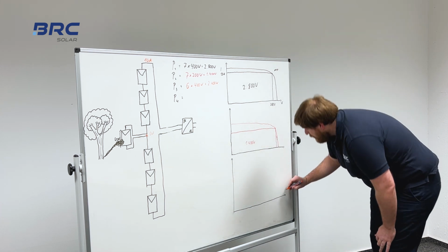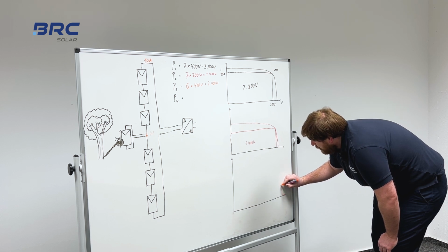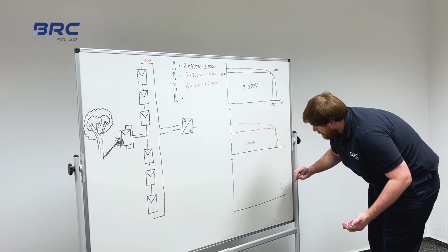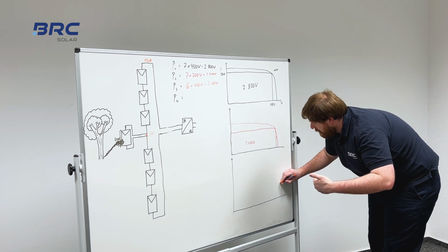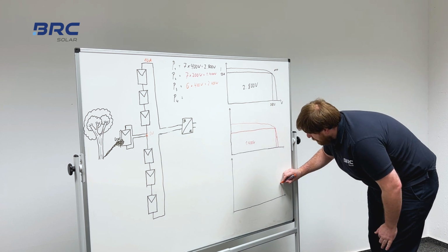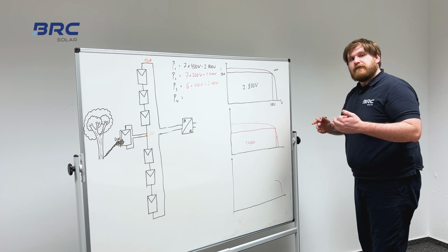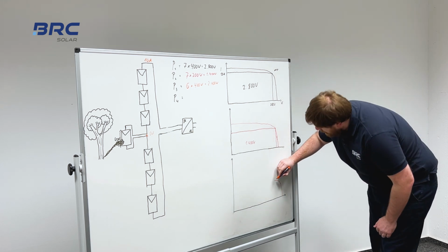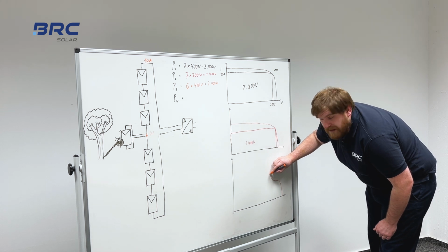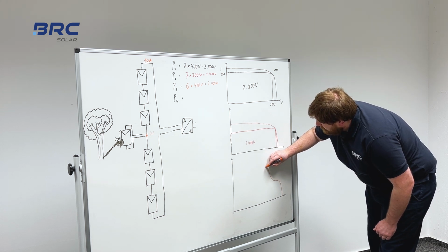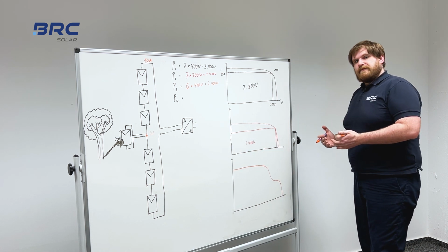It's like before, the inverter starts by increasing the current and looks for the MPP. It finds there is at least one module that can produce just this 5 amps, but then it increases the current over this 5 amps, and we see that now the voltage decreases a little bit by the bypass diodes. It decreases by 1 module. And then by decreasing the voltage, now the inverter is able to increase the current back again to the level of 10 amps. And now the inverter finds 2 maximum power points.